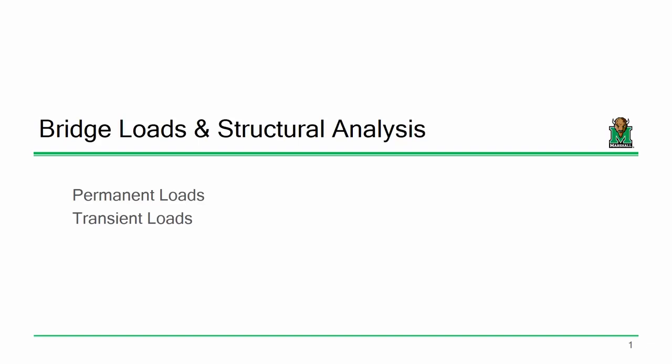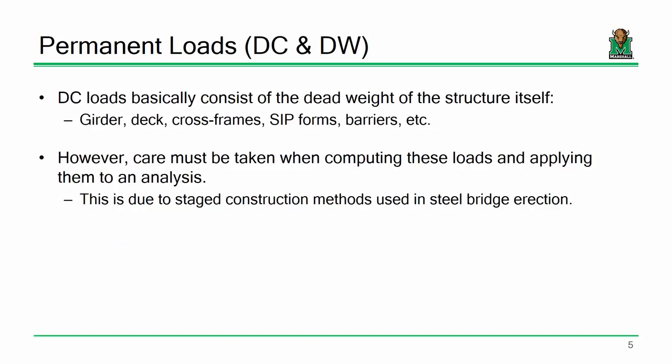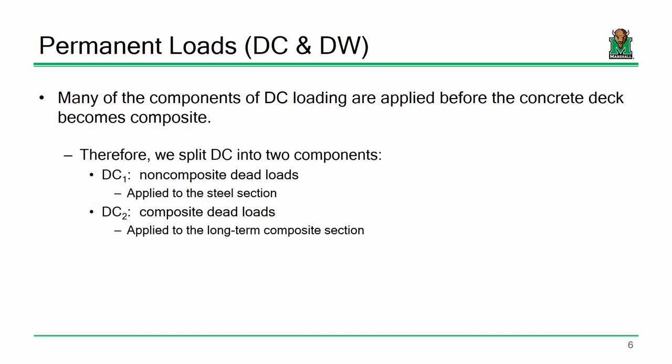related to bridge loading. Now, there really wasn't a whole lot to say on permanent loads. It's just the self-weight, pretty basic stuff, really. I mean, take the unit weight of a material, multiply it by the area to get a weight per foot, stuff like that. And a lot of the load computations that we did for dead loads fall mainly on common sense, just pretty basic ideas. As long as you're keeping track of units and you're just assuming all the load gets equally distributed to each girder, it's not tough. It's pretty straightforward stuff. So there really wasn't much discussion about the dead loads other than they're there and we need to compute them.